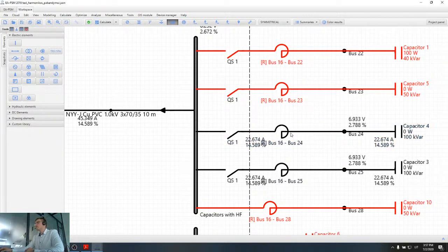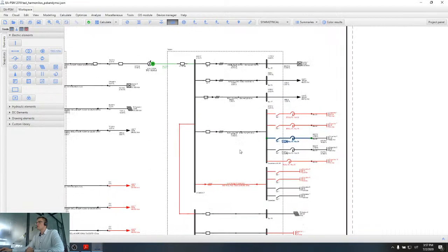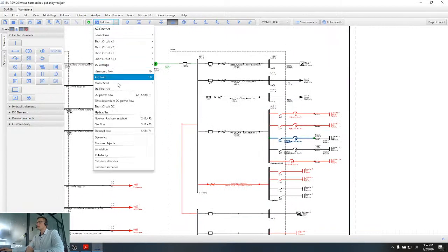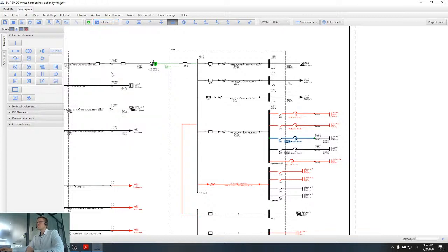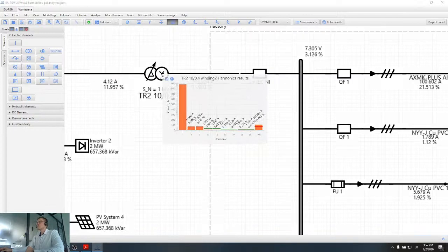How to select what size of the impedance you should have? You can do this using the software. For example, I can select smaller impedance values. Instead of 6%, I will specify 2%, which is actually giving me the smaller impedance value, and I can check whether this kind of frequency is enough for my harmonic mitigation. I can see that with 2% impedance, still some of the harmonics exceed the permissible limit, which is not good.